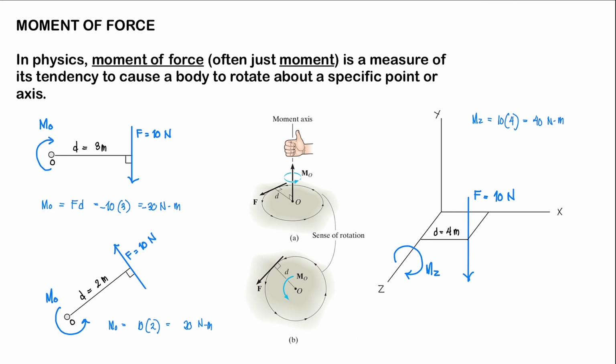So the force F, 10 newtons, multiplied by the perpendicular distance or the moment arm, and that is equal to 2 meters. As the name suggests, the moment arm or the perpendicular distance is perpendicular to the force, up to the axis where we are considering our rotation. In our case, we're considering the axis perpendicular to point O. Alright? So, our moment O is equal to 10 times 2, or 20 newton meter.